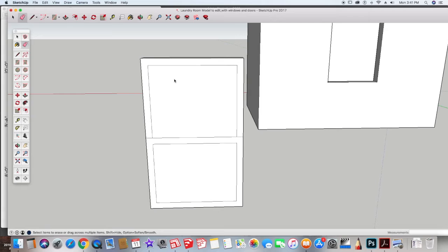The next thing we have to do is divide this upper line into 3 segments. That could involve a lot of math and get kind of confusing, but SketchUp is really, really good for this, because it'll divide it for you. And to do that, using the pointer tool, you're going to click the top segment there to select it. Then on your 2-button mouse, you're going to right click and click divide.